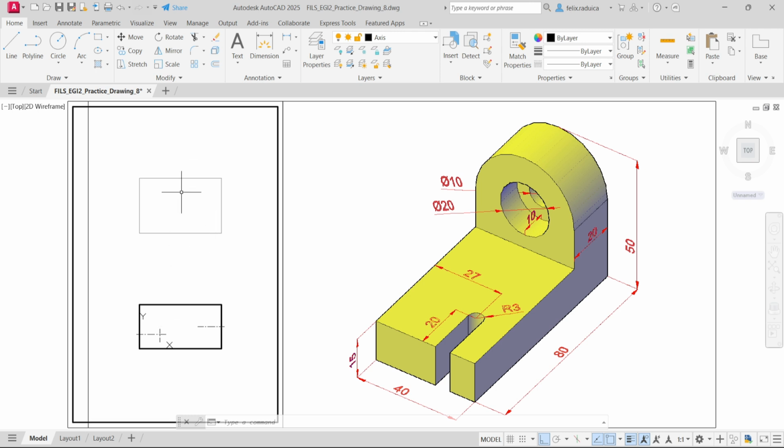And so to draw the axis line in the top view, I'll have to give the line command and start from this point here and go like that up till I want to go perpendicular, so PR, and click here, tap enter. So I managed to get the correspondence.